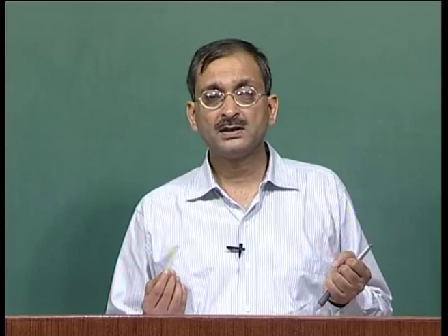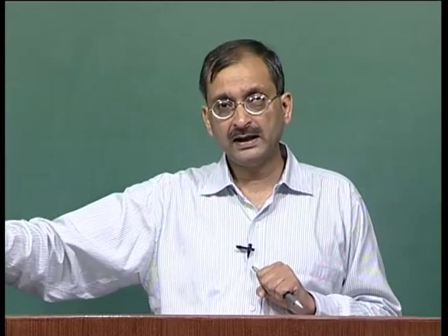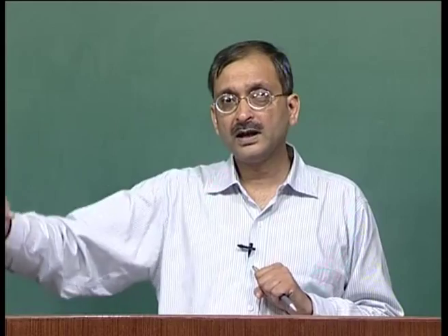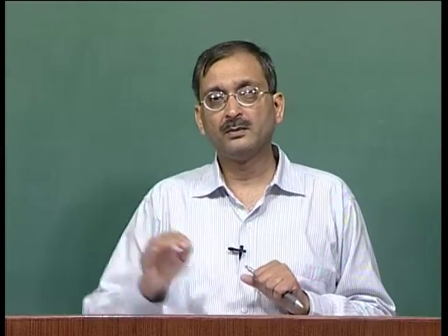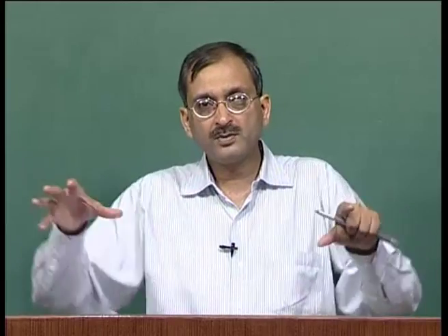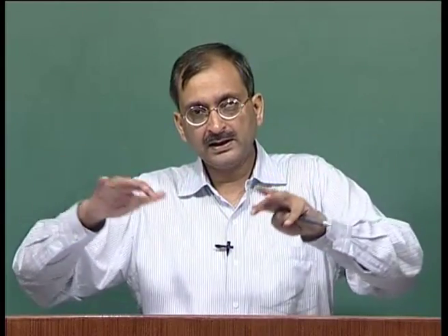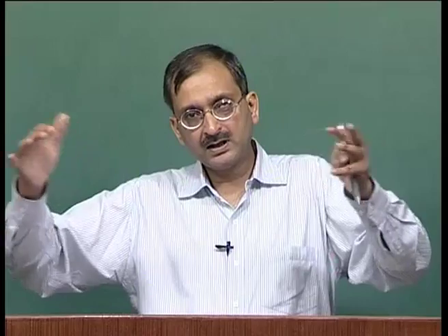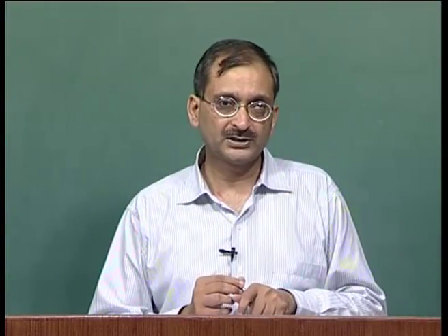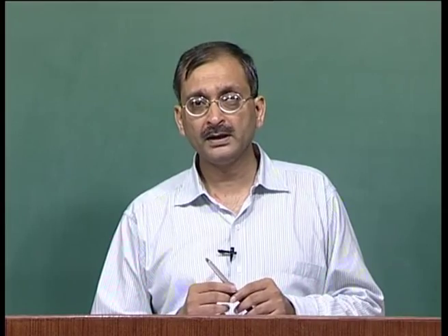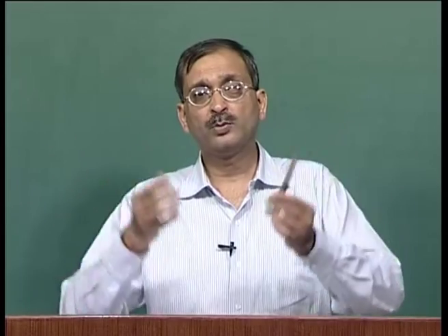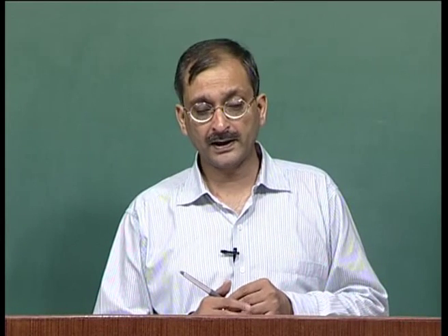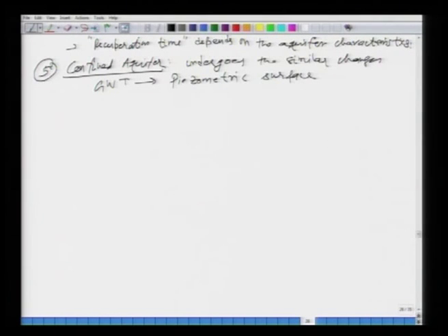And what is the piezometric surface? Well, if you dig an observation well, the water will rise up to the piezometric point, or the energy whatever is available. So, if you dig lots of observation wells, you can see that the piezometric surface will form that cone of depression, which will become constant after prolonged pumping, and after you have stopped the pumping, things will start to recuperate back again in the observation wells. So, exactly the same thing is going to happen.